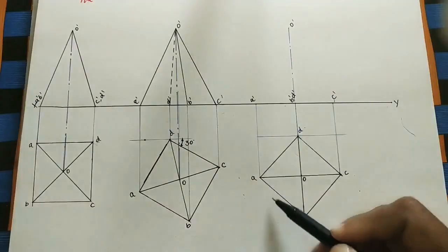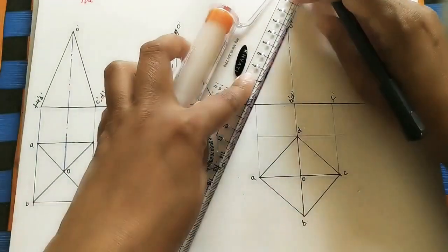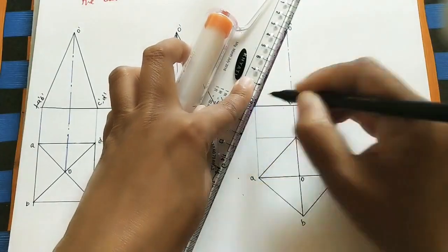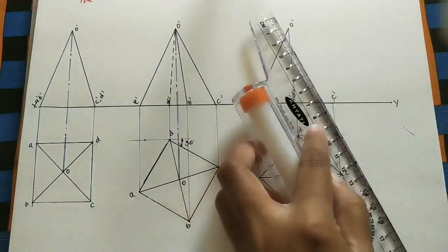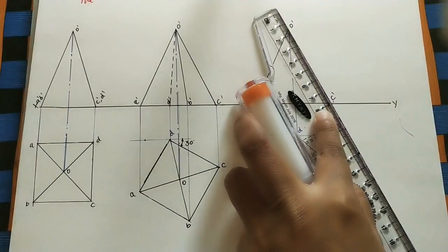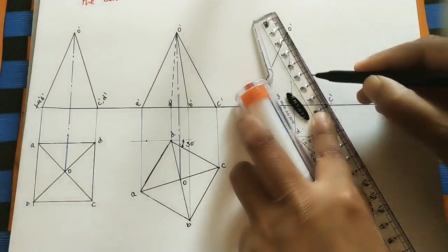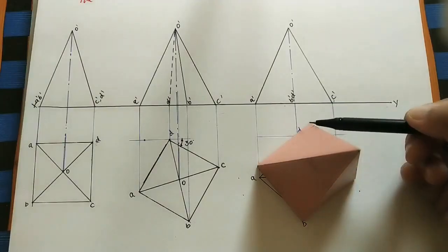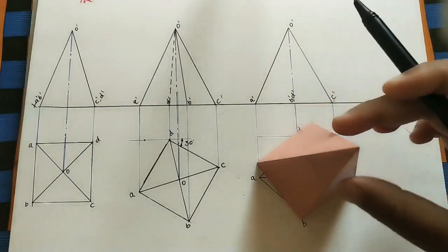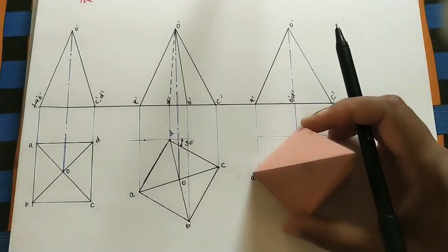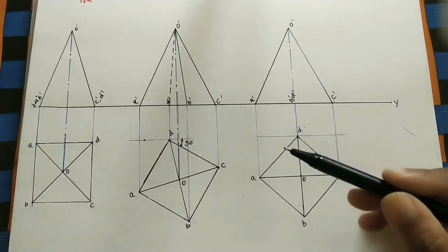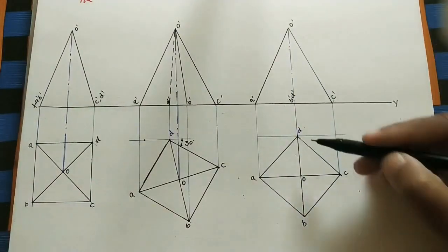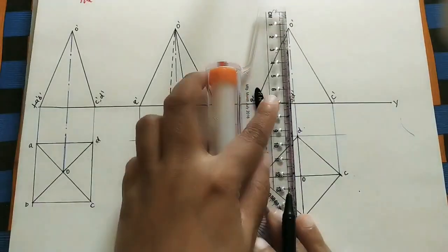The corner A we can see from the front. Do the continuous line. And C corner also we can see, a slant edge. So from the front we can see this edge, but we can't see this edge, but both are coinciding on the axis line. Okay, so here this edge and axis are coinciding. So here this is visible, that's why do the continuous line here instead of the axis.